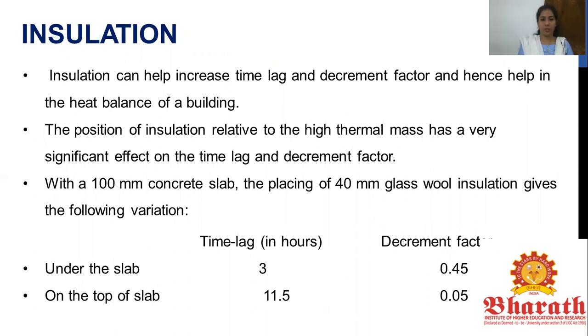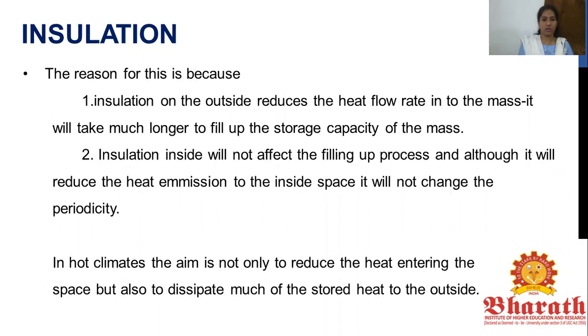So with a 100 mm concrete slab, placing 40 mm glass wool insulation gives the following variations. If it is placed under the slab, the time lag is only 3 hours, whereas if it is placed on top of the slab, it's 11.5 hours. How does this actually affect you?